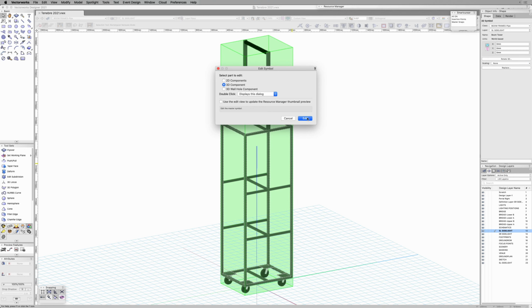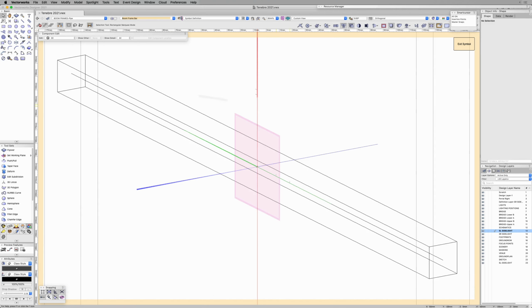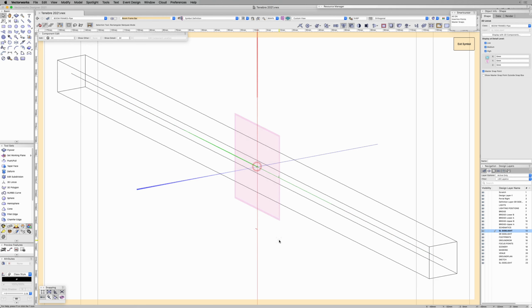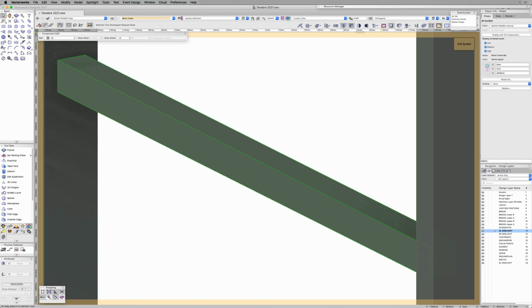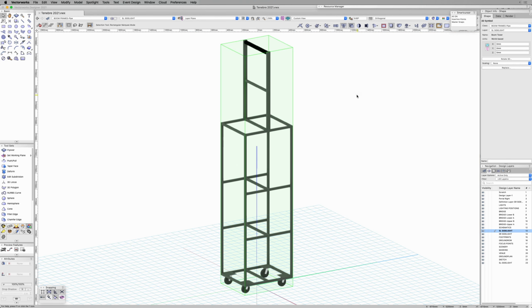There are also some nested symbols with the geometry. These are primarily for using as objects to attach lights to, and they contain a toNURBS curve for using as a smart edge when aligning lighting devices, as well as a 3D locus which I have set to be a master snap point. This makes it much easier to attach lighting devices, as master snaps are designed to take priority over other snaps but won't be visible until the cursor finds them. Ultimately, it's all about decluttering.